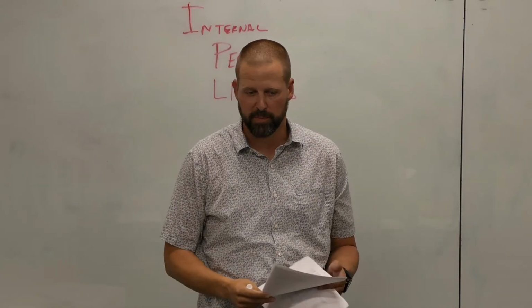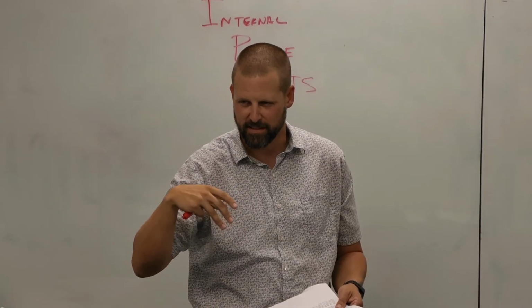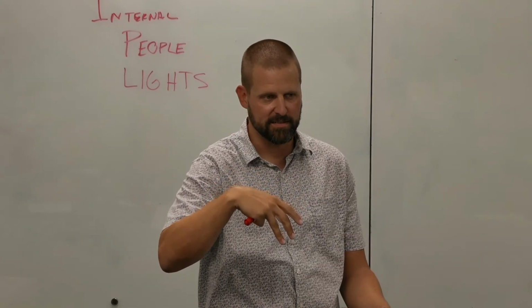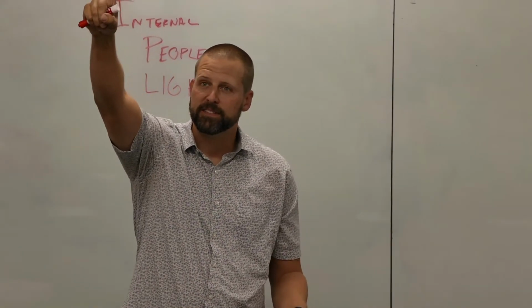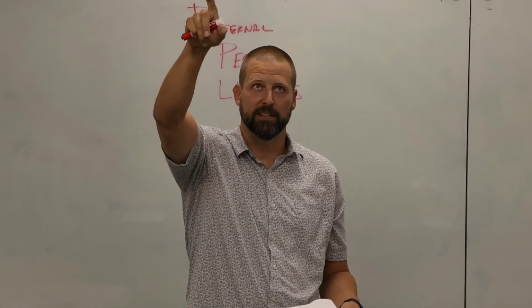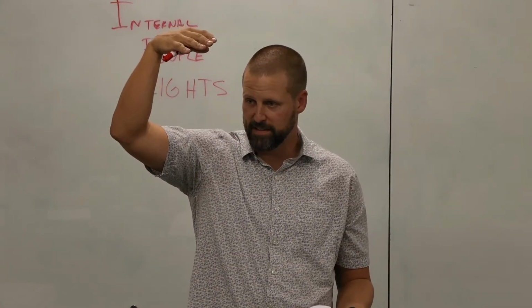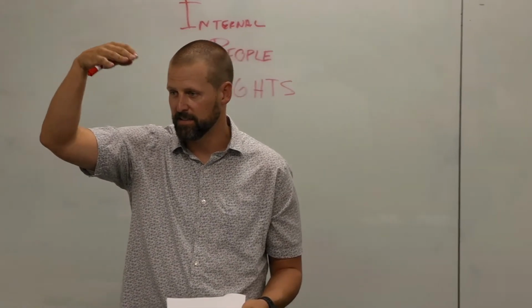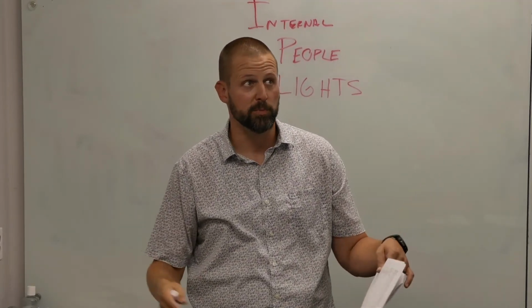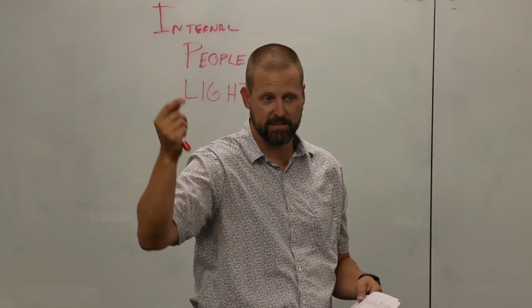They also could be desk lights. You don't see a lot of those, but a lot of times people will have individual lights at their desk. The other discussion we think about is the heat from this light doesn't just come out and into the room, it also has a ballast behind it. So a certain percentage of that heat goes to the plenum, and there's a difference in how we treat the room. The room we have to condition by blowing cold air. The plenum is picked up in the return air.